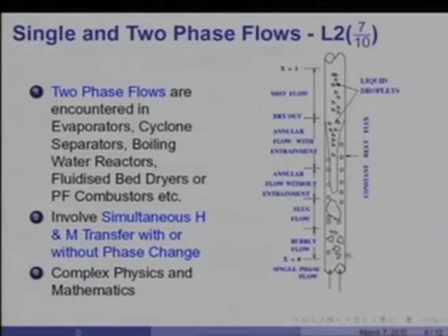Such a zone is called the bubbly flow regime. As we go downstream, the temperature of the wall continues to rise, and the number density of bubbles also increases, so much so that some of the bubbles actually coalesce with each other and form large bubbles, which are confined and surrounded by smaller bubbles. The large bubbles move like slugs, and therefore such a region is called the slug flow region.